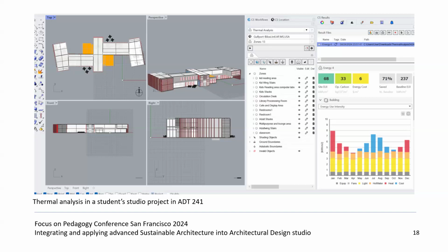But based on the materials they use, because they also use other applications to design a wall based on the R value and U value, and they also bring enough daylight to turn off the electric light during the day, and they also use a more efficient mechanical system like the heat pump with the higher efficiency, the site EUI is actually 68 kilowatt hours per square meter. So they start to save energy, about 75%, based on what they have.